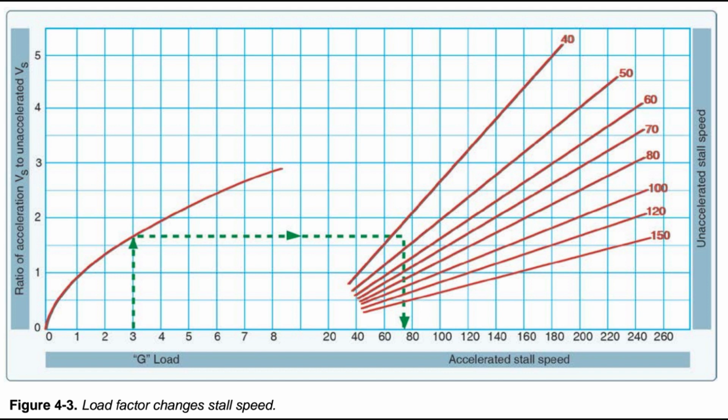Weight control. Weight is the force with which gravity attracts a body toward the center of the Earth. It is a product of the mass of a body and the acceleration acting on the body. Weight is a major factor in aircraft construction and operation and demands respect from all pilots. The force of gravity continuously attempts to pull an aircraft down toward Earth. The force of lift is the only force that counteracts weight and sustains an aircraft in flight.